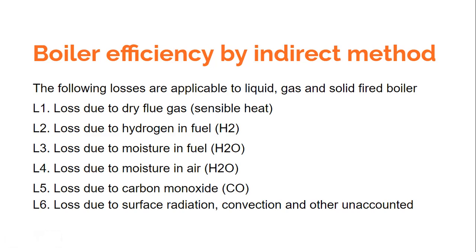Now, when you have carbon monoxide as a product instead of carbon dioxide, it would release less energy as compared to the case where you are forming CO2. Because formation of carbon dioxide as well as formation of carbon monoxide are both exothermic reactions. Exothermic in the sense that energy is released. However, less energy is released if you are forming carbon monoxide, and more energy is released if there is formation of carbon dioxide. So when you are having carbon monoxide in the products of combustion, there is a loss.